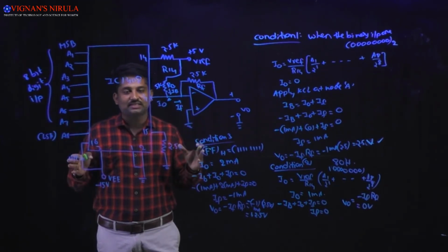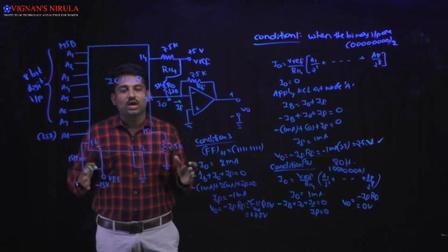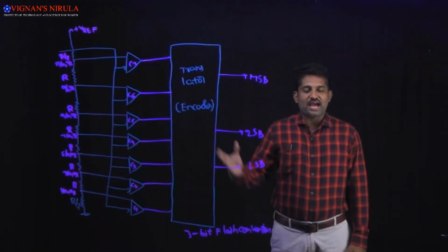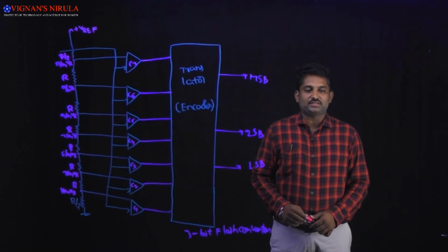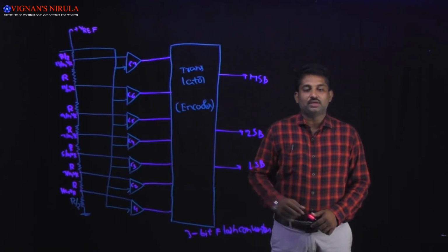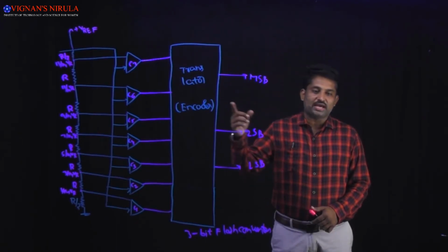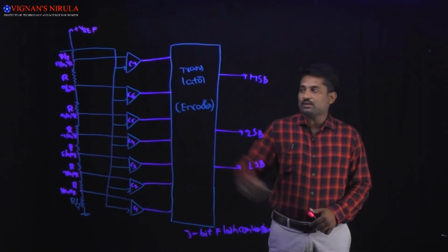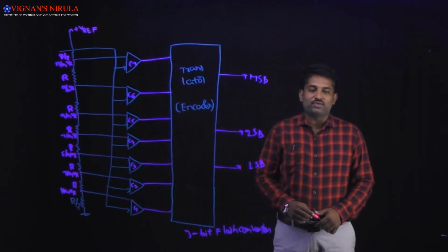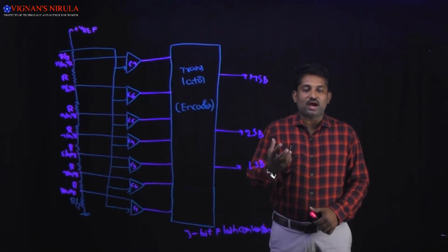The IC 1408 DAC is an 8-bit R/2R ladder type DAC technique. Flash type ADC converters: when the system design calls for high speed, then the flash type ADC converters are the right choice, and they get their name because of their ability to do the conversion very rapidly. Flash type ADC converters are also called simultaneous converters or parallel comparator converters.